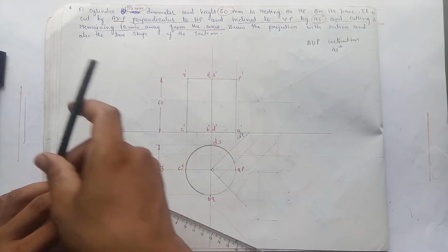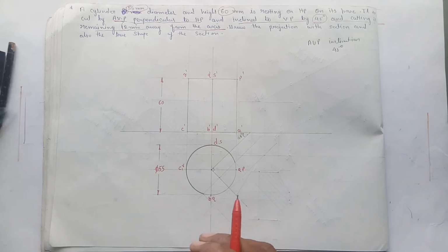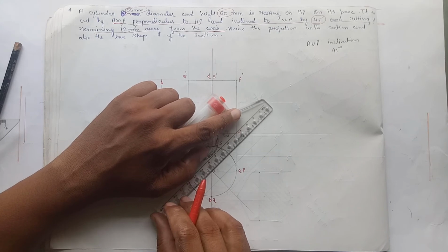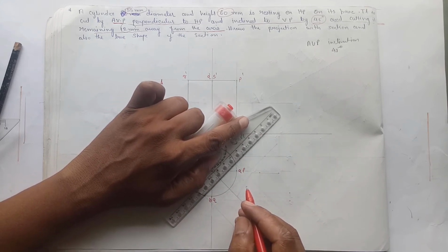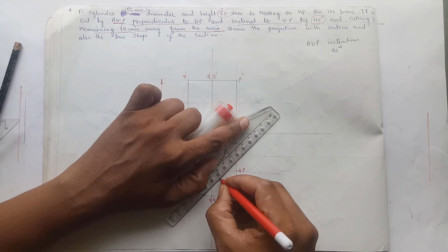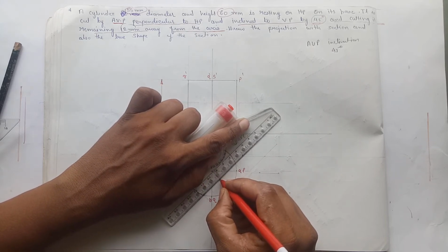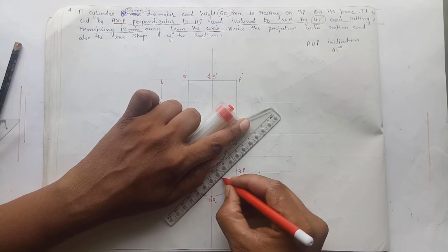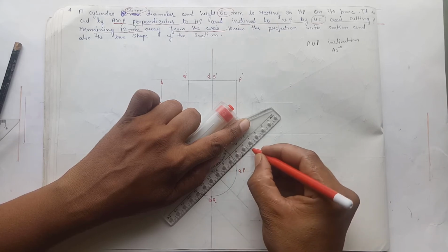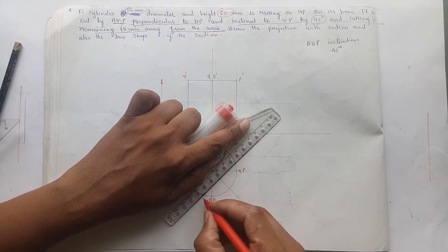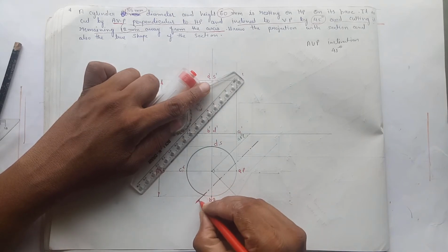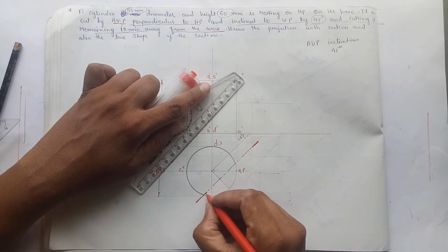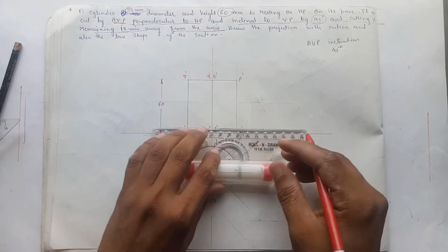This will be the plan of the axis. Now show the cutting plane, which is inclined at an angle of 45 degrees. If we draw a line parallel to this line, the angle of that line will also be 45 degrees. So from this point, which is 12 mm away from the center, show the cutting plane over here. We have to darken the ends, because to show the cutting plane line, we use a line thick at the ends and thin elsewhere. We can also say that it is a cutting plane line.